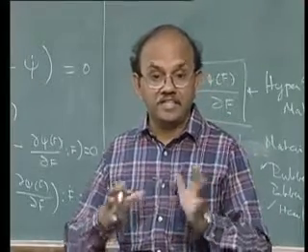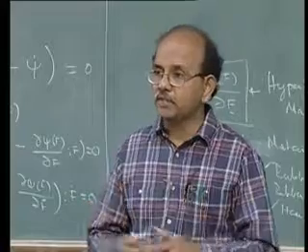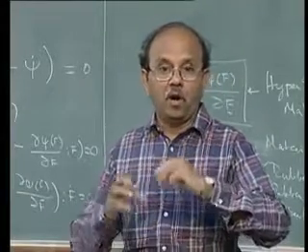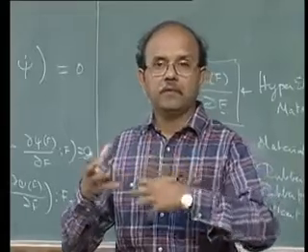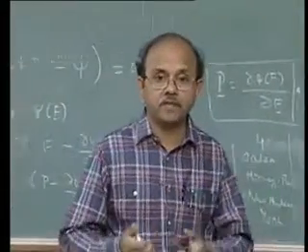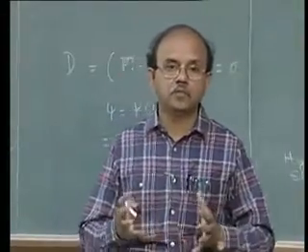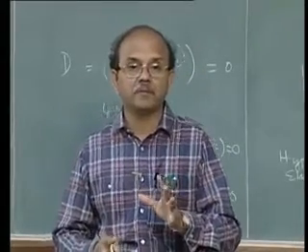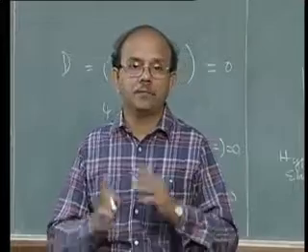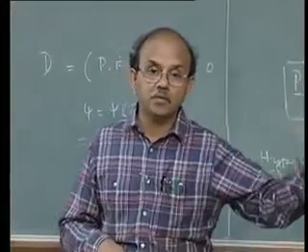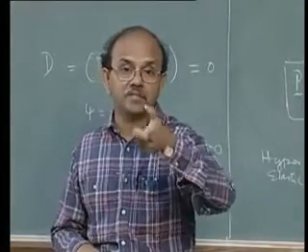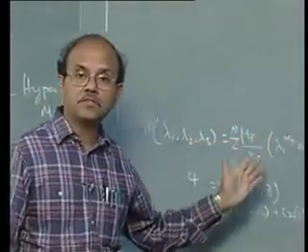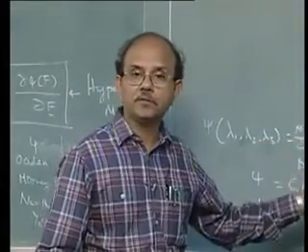So the testing of these materials means that we are interested in the mechanical behavior, not in how the structure inside, the isomers or whatever is inside, behaves. We are not interested in that. It is mechanical behavior on a gross, macro scale. So you have to understand them using all these test results and then fit the constants to a particular equation.